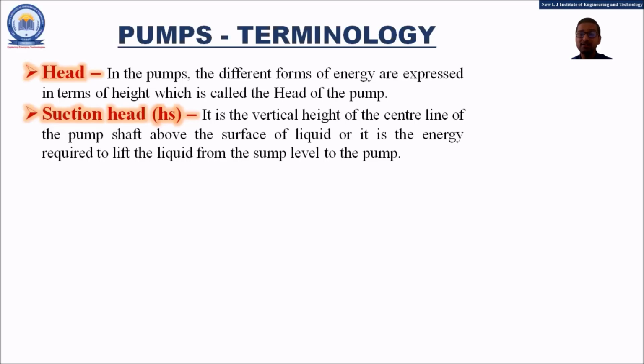The suction head is the vertical height of the center line of the pump shaft above the surface of the liquid. So it is considered as the height from the sump level, that is the suction tank, to the center of the pump. That height is considered as the suction head.